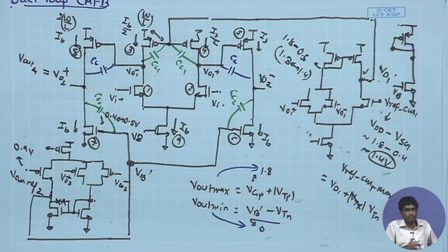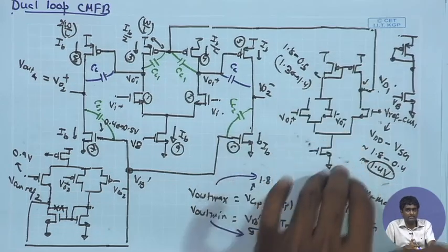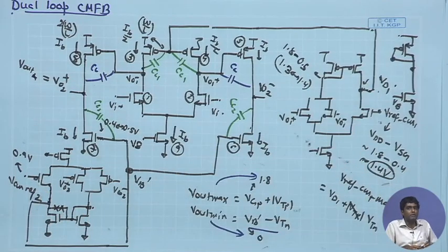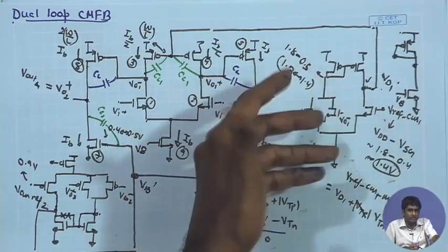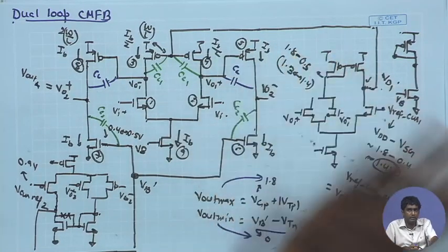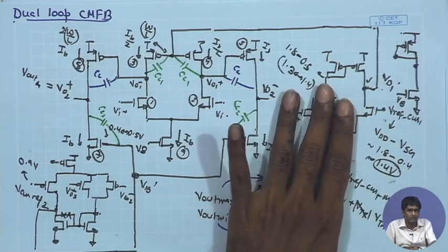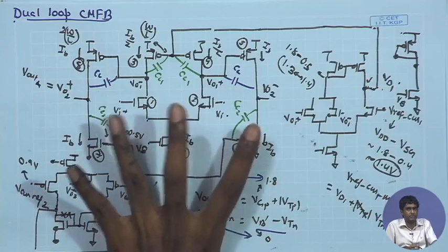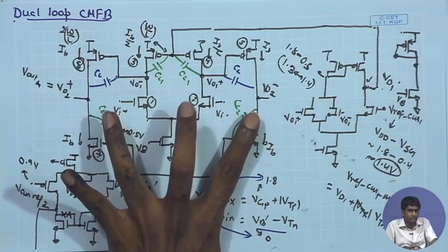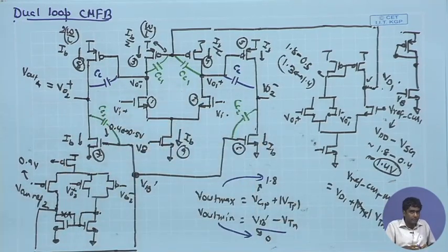So, if you are, for example, trying to keep the bias current in these error amplifiers lower, in that case the bandwidth over here will be lower, and after compensation you will be getting a lower pole over here. But for the differential operation, you may have a bandwidth requirement, as the signal coming is much faster. You would like to maintain a probably larger bandwidth for the differential case.